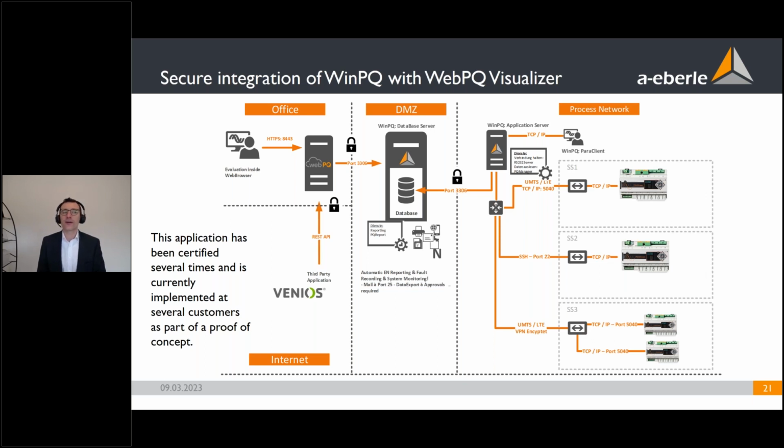So there is no need for a really high data rate to the meter itself. This is because of our experience, and we know that communication is often the main issue. Therefore, we also provide other solutions. You can see it on the PQI-DA Smart, for example. Some devices, inside the standard parameterization and without any communication, can provide the long-time medium average data over 140 weeks without any break, so approximately 3 years. Then, if you connect the device to the database, we need some time to read out the data, but there is no need to extend the bandwidth in a big way.